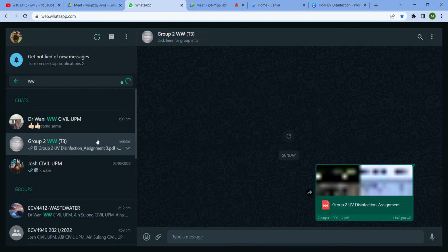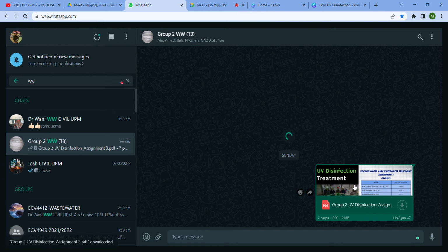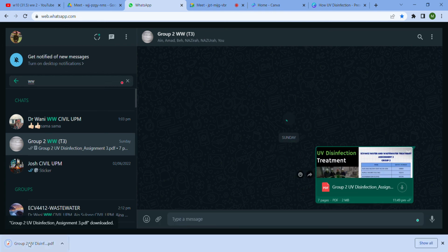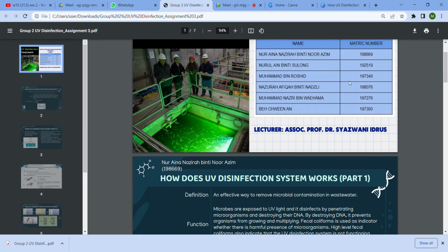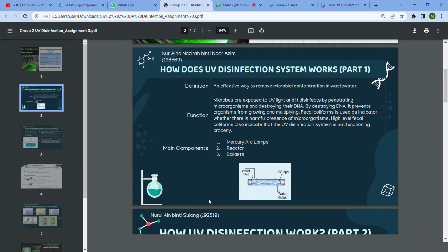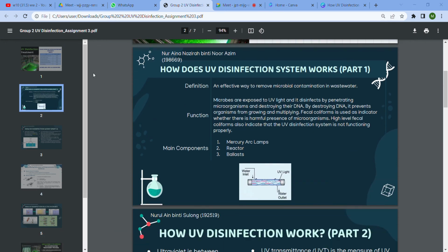For each intake site, salinity and other fluctuating parameters that affect appropriate operation of the desalination systems must be examined very carefully, as fluctuations of salinity, density and temperature are of importance for the smooth and efficient operation of any desalination system. That's all from me. Pass to my friend. Okay, thank you.